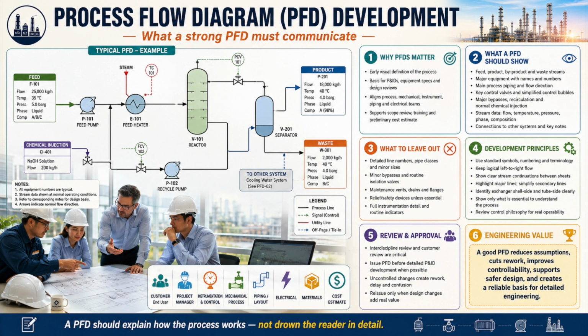Ideally, the PFD should be issued for design before P&ID development begins. Projects sometimes start P&IDs early to protect the schedule. This may appear to save time, but an unstable PFD transfers unresolved decisions into a much more detailed document. A single PFD change can alter equipment connections, line lists, valve counts, control loops, relief cases, instrument indexes, cause and effect logic, layouts, cable schedules, and cost estimates. Starting P&IDs before the PFD is sufficiently mature usually creates more work, not less.